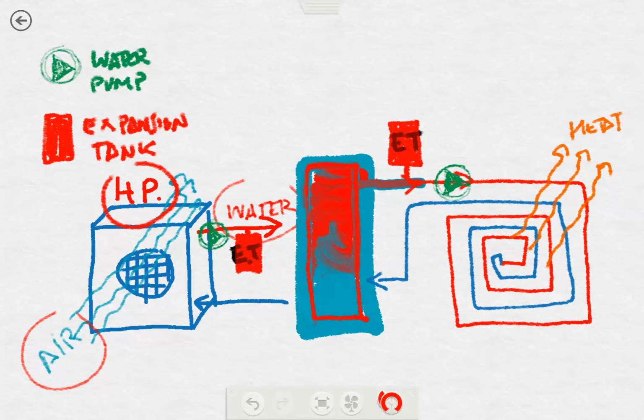So the heat pump needs to work for, let's say, a couple of hours. Okay, so we need to increase the amount of water that we are heating up. So that's why we need a large amount of water, because the amount of water that we have in the radiant floor, it's not that much. So if we had only the water on these pipes, the heat pump will be starting and stopping continuously, and this is not good.